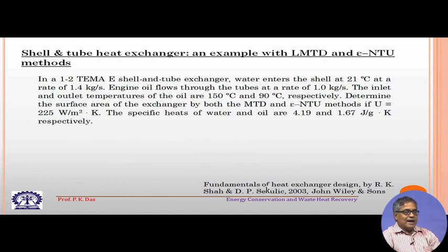It means that the tube side fluid traverses the shell length 2 times before it goes out of the shell and tube heat exchanger. TEMA E shell, obviously you can understand E is some sort of nomenclature for a particular type of heat exchanger, and TEMA is the Tubular Exchanger Manufacturers Association. So, this is a body for having different kinds of codes and standards for heat exchangers, specification of heat exchangers, design of heat exchangers, etc.